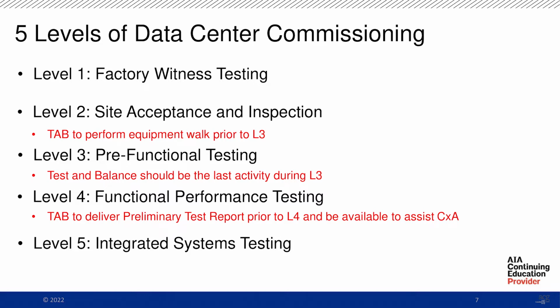So like I said, TAB, during the L2, we'll do a walk, check out the equipment, make sure everything is in the right spot, valves, dampers, for the few dampers that we do touch, make sure the equipment's going the right way, make sure everything's spinning the right way. L3 is where we do the most of our testing. So during L3, the mechanical, electrical will start up the equipment. The controls group will come in and do their own sequence testing, their point-to-point, and then we'll come right there at the end when those 2 things are done and bring it all together.